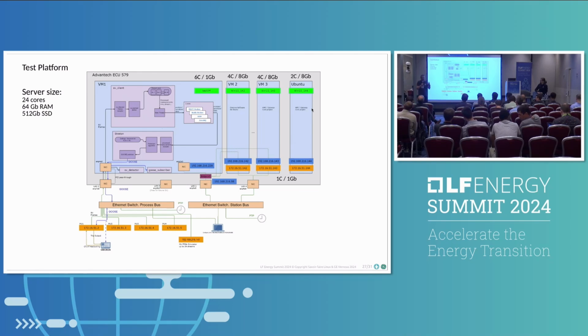Yocto, let's say, gives you more freedom to customize, if you need to customize something. At the end, a hypervisor is something that has to be very, very light. Okay, all the power and the intelligence and the IP remains on the virtual machine. The hypervisor is only a virtual machine manager. It has to do nothing else. Okay, so Yocto gives you the possibility of making the hypervisor very, very light to comply with your requirements.